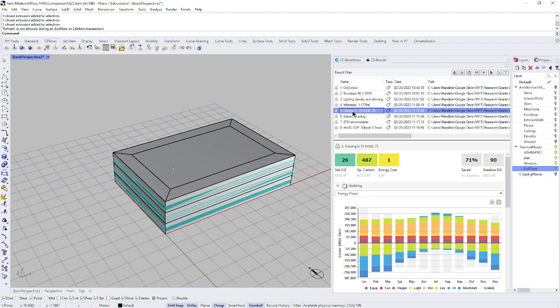Next, I changed my glazing. I used a triple pane, really low U value, but a high solar heat gain coefficient. So we're getting the benefit of solar heat gains when we need them. And that did a pretty good amount, from 35 to 26. So our glazing helped a lot. Then I added some exterior shading. I didn't spend a lot of time on it. There's a setting in the model that you can set. It didn't change it much. I should probably go actually set some real shading and see what I could do, but I'm already at 73% less than the baseline.